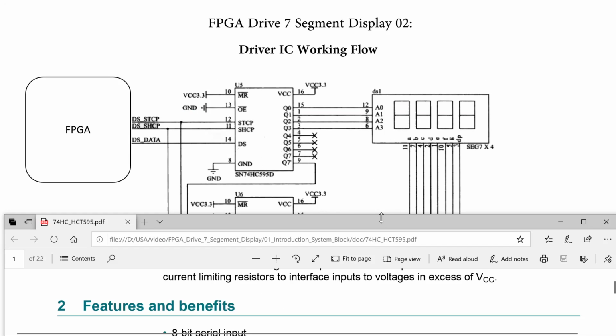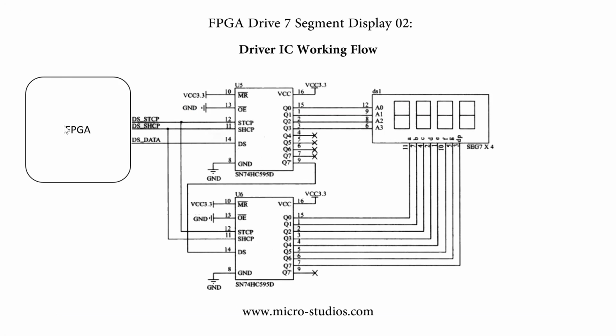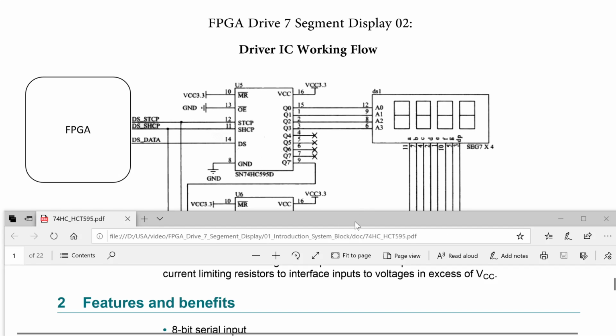We can use the FPGA clock directly to drive this and this logic IC. Our board is 50 MHz, so we can use it. This is the first thing.